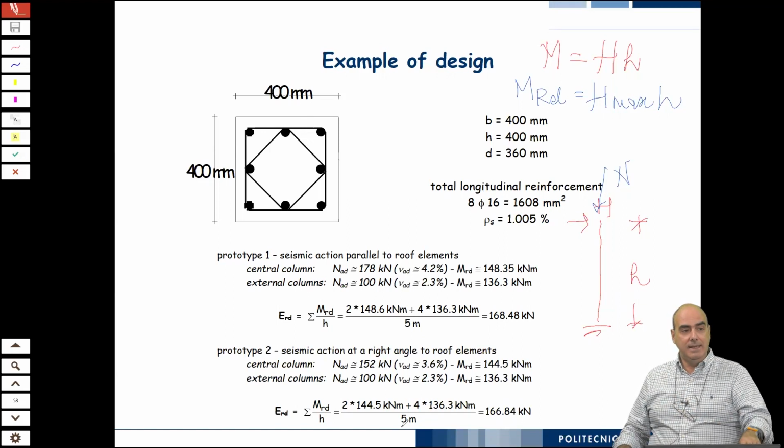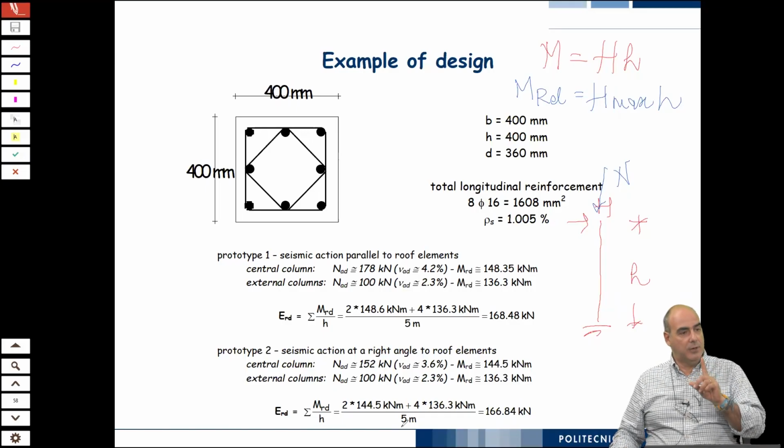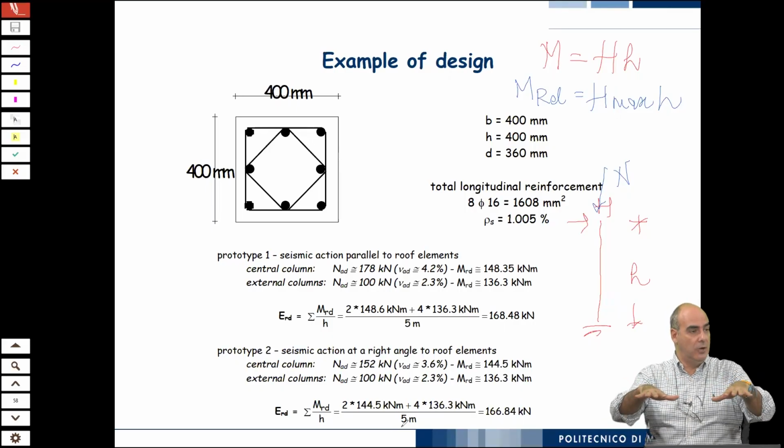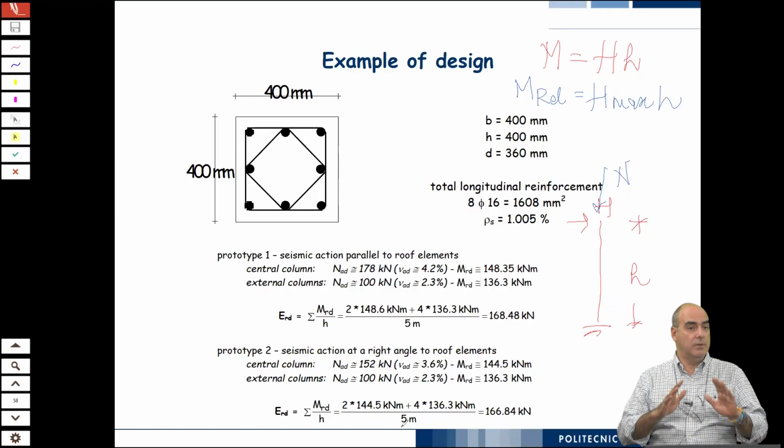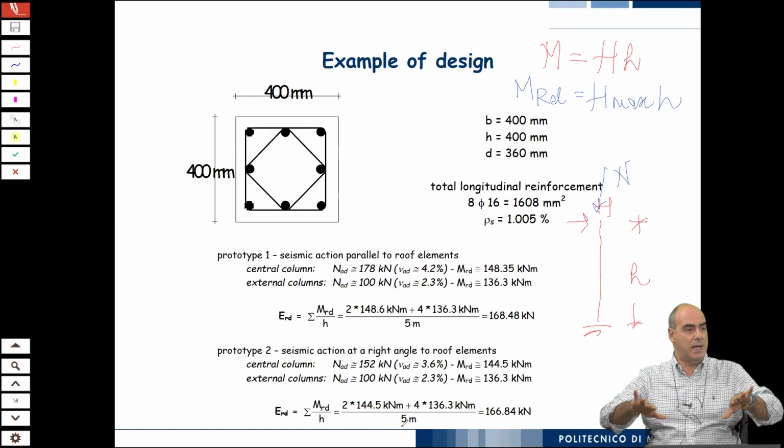So in the end, this is a very important conceptual assumption that we checked. When we redistribute the loads, in the lecture that we did, I think on Monday or Tuesday, I don't remember, we said if you have different elements, you distribute the lateral load proportional to the stiffness. In this case, forget the fact that sometimes we had the walls.